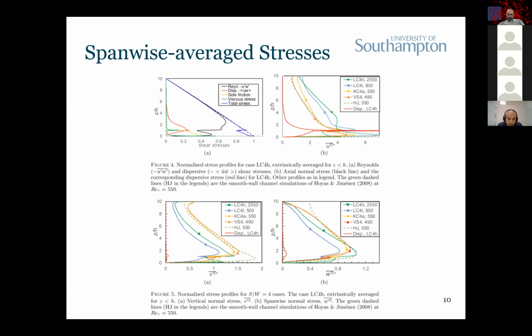It's a very significant deviation from the smooth channel, whereas higher than that, 2 times the rib height, the agreement with the smooth channel is restored. Apart from the very high Reynolds number case and the blue curve, which is Re tau equals 500, but that case was made based on a very small domain size, so that wasn't producing the same trend.